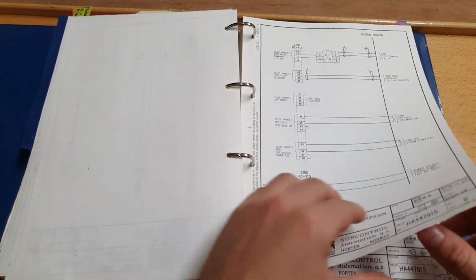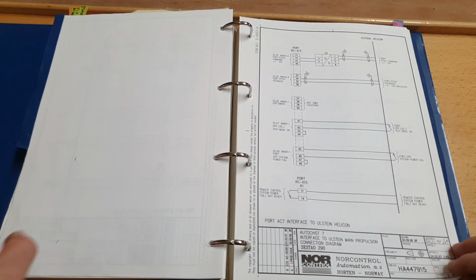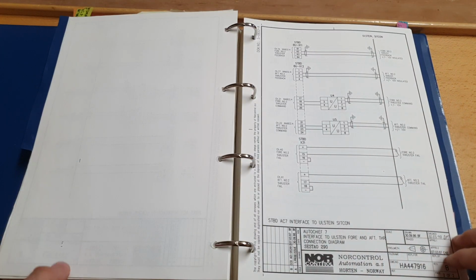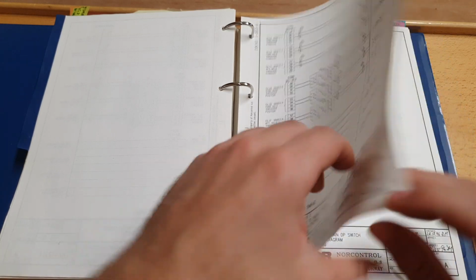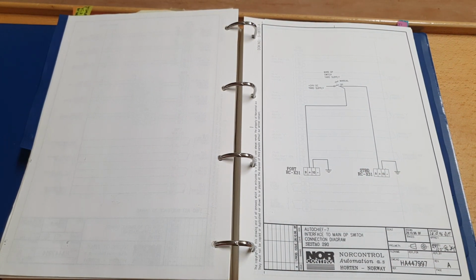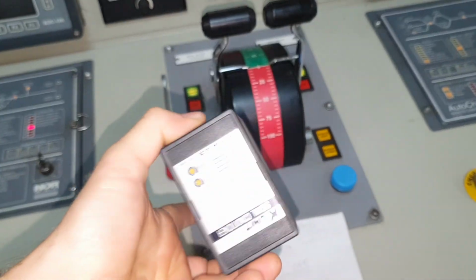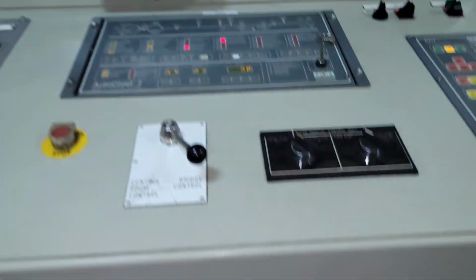On the next page in this manual we see the signal converter. There are 12 converters in the system, 6 of them for each of stern, bow, main thrusters, and the rest 6 in order to transmit signals from DP computers. Now we need to find and check the converter that is responsible for the faulty thruster. The location of converters is not specified in the manual, but it was not difficult to find it. They are installed in the center consoles, on the navigation bridge and engine control room consoles under the double maneuvering levers. Replace the converter, then acknowledge the CPP control failure alarm and proceed to test the system